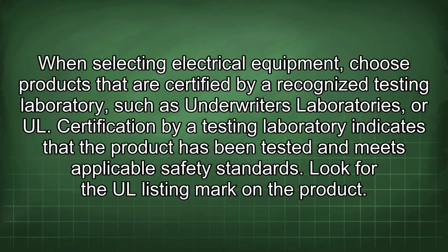When selecting electrical equipment, choose products that are certified by a recognized testing laboratory, such as Underwriters Laboratories, or UL. Certification by a testing laboratory indicates that the product has been tested and meets applicable safety standards. Look for the UL listing mark on the product.